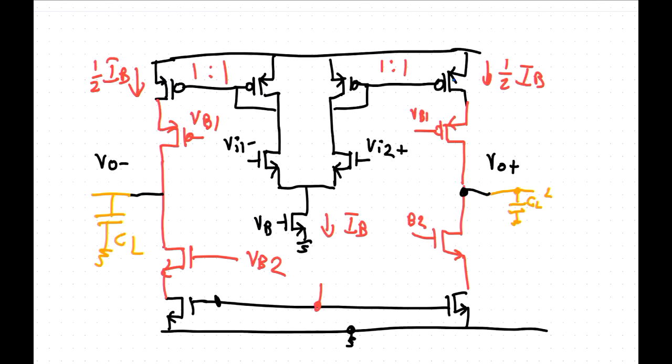But now we get into the problem that was mentioned in the book. Now we actually have essentially a current source up here and a current source down here. And if they are not identical, say the bottom one is a little bit larger, this node is just going to slam and cause this to go out of saturation into the triode region. It's not operating properly any longer. See, this is now a problem.